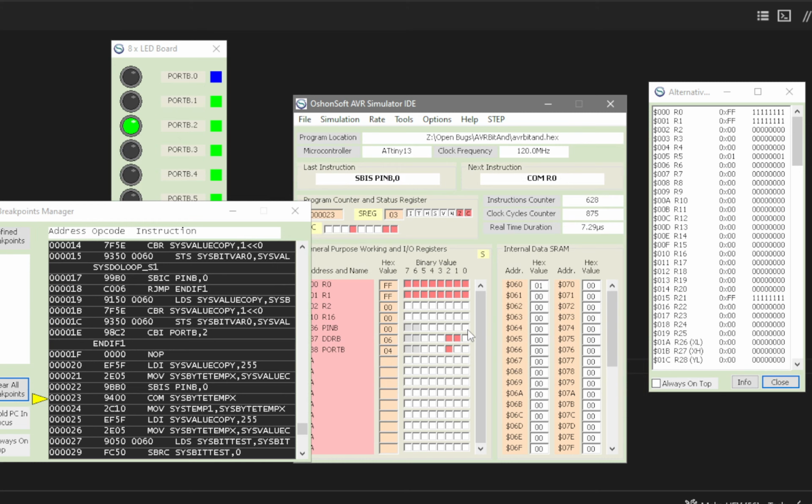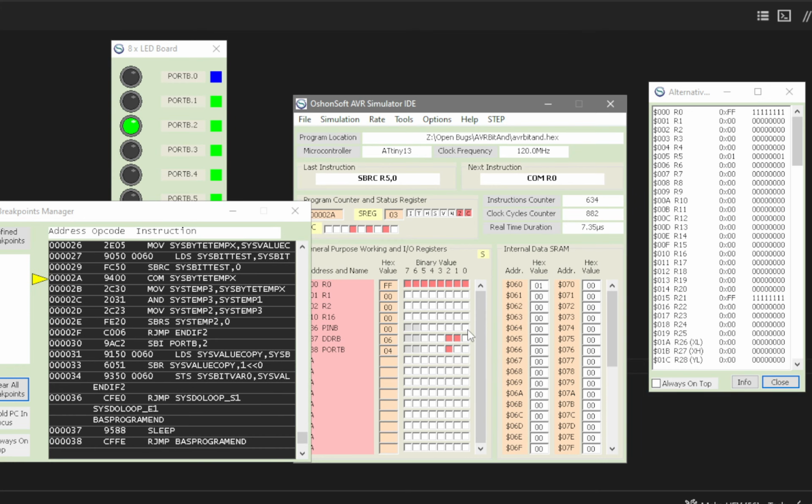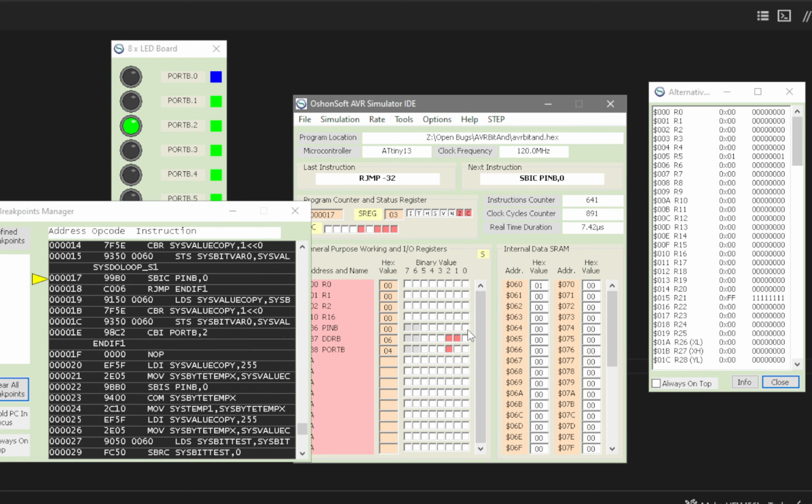Now, because I've just unset it, it's going to take that temporary variable that was always set to high and turn it to 0. Now the AND test is very different, because it now says the latch is 1, but the port is 0. So it turns the LED off. When it exits from this routine, the top routine he wrote, it turns off the LED and clears it.